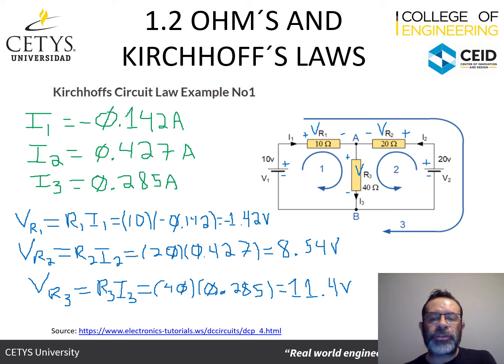And also, if you notice, let's talk a little bit about the signs. So what's happening here is the following. I1 is negative. The only thing that means is that the original direction that we identified I1 as this way, really I1 is going this way. So the sign just means it's the other way around.